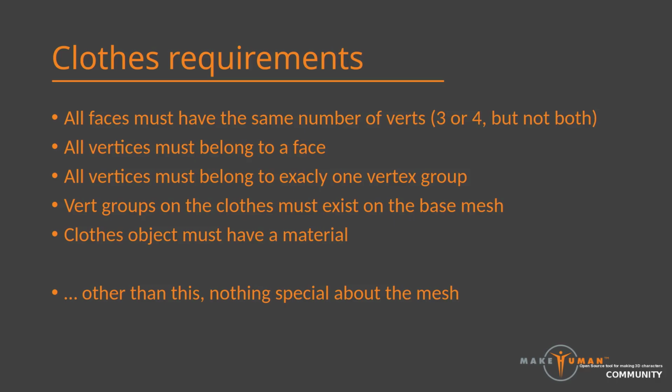As you can see, no particular magic was required. A standard plane could be used as clothes, after we had assigned a vertex group and added a material. There are some requirements on the mesh, but they should not be difficult to fulfill. The most common hurdle new tailors tend to run into is that they mix faces with different number of sides. It is acceptable to use tris or quads, but you cannot mix them in the same mesh. Faces with higher number of sides are not supported.